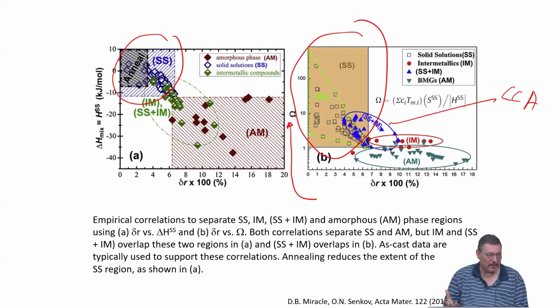So you maybe have to think about how your cooling method is affecting the crack formation, whether you need some stirring, things like that, or whether you need to do maybe Bridgman solidification to avoid that, to get closer to equilibrium configurations, which avoids building up stresses so much.